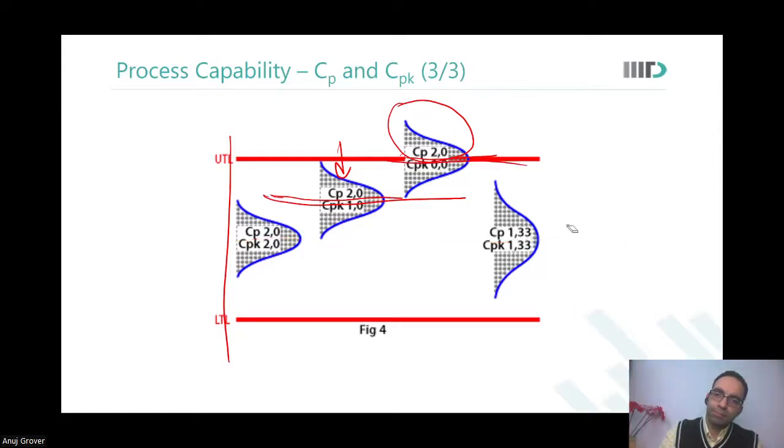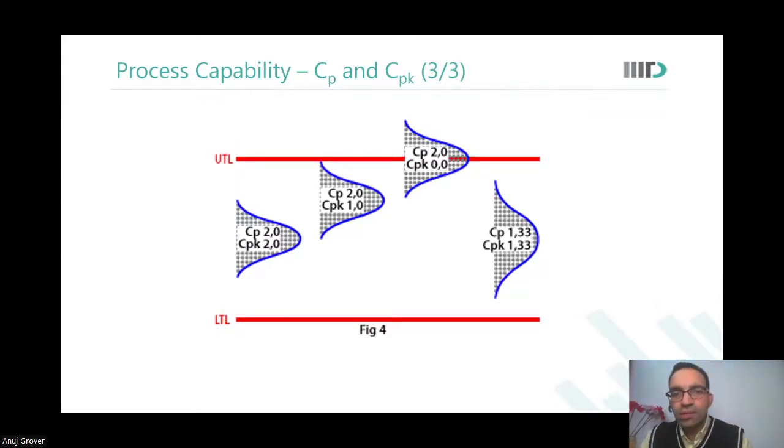Yes, sir. But I got confused because you mentioned the example of length, which we actually use to control random. Oh, but all devices get etched in terms of poly etching simultaneously, is it not? Yeah. So if poly etching is done simultaneously, then if, for example, you etch the particular die for 1 millisecond more, what happens? Length reduces. All the devices will now be towards fast. So these systematic length variations would lead to systematic shifts.